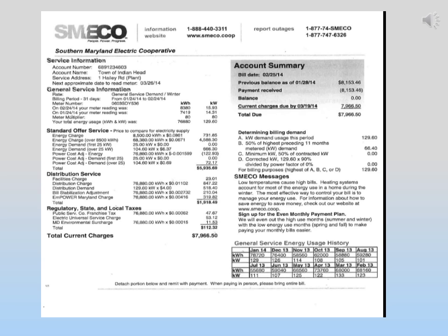If we are working on kilowatt hour savings, at what rate are we saving? This is a significant part of what we need to be able to grasp and understand. Are we saving at 6 cents per kilowatt hour or 8 cents per kilowatt hour? We are saving at the 0.6 cents per kilowatt hour because no matter what we do at this point, we will never get below the 8,500 kilowatt hour minimum unless we start turning things off completely. So in this case, we are going to be saving roughly 0.67 cents per kilowatt hour.